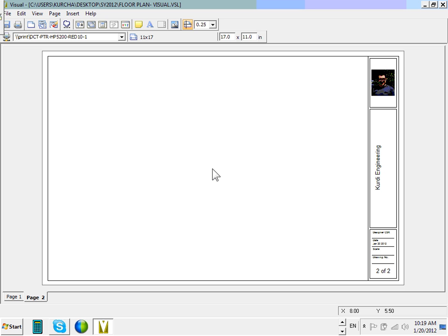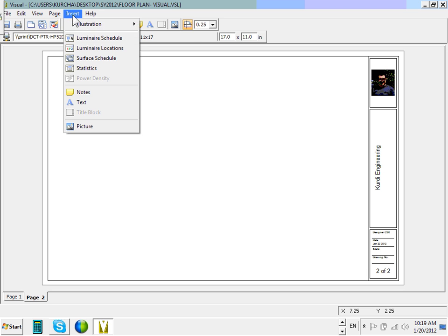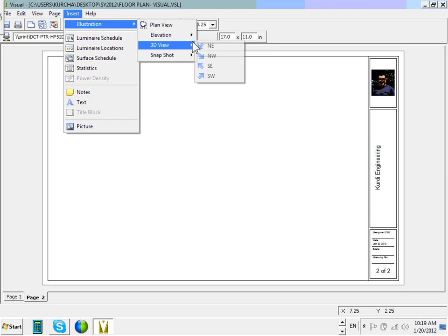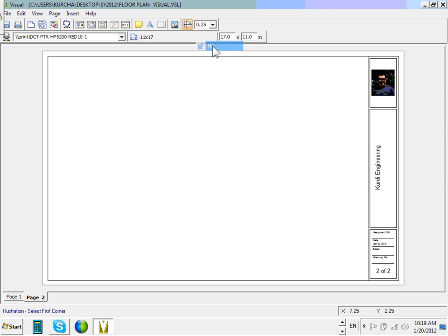Okay? Let's go get a 3D view. Insert, 3D, illustration, 3D. Now which 3D, Chad? I like Northeast. Does it matter to me? It doesn't matter which 3D to bring, right? Give me one that has Northeast or Northwest or something. I'm going to go grab the first one, Northeast. It really doesn't matter which one to bring. Now I'm holding a Northeast in my hand.